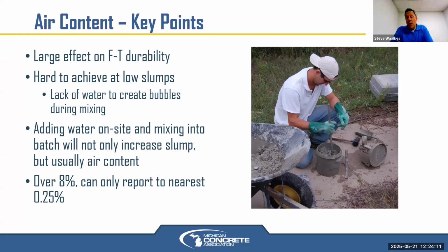The problem is the less water you have, the harder it is to get a good air void system. So with low slump, low water-cement ratio, just very little water in a mix, it's harder, because of how the air entrainment admixture works. Think of that as Dawn dish soap, or your favorite brand, Costco brand in my house.